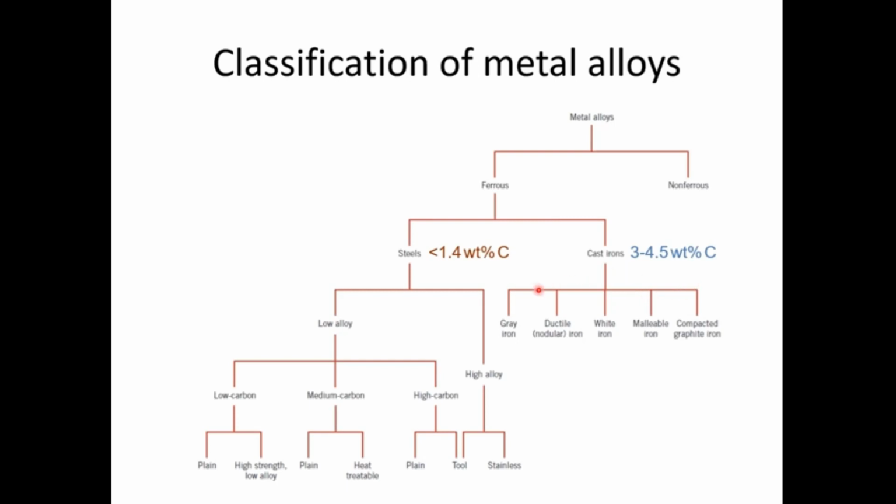So as we compare between these two, cast iron normally has a lower melting point as compared to the steel, and therefore cast iron is easily melted and easy to cast. And therefore, since some cast irons are very brittle, casting is the most convenient fabrication technique.